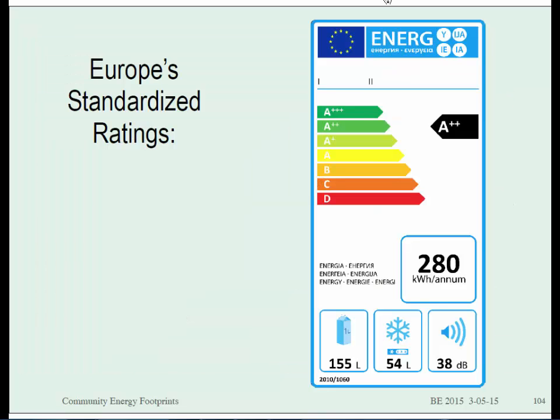As HERS ratings are not particularly informative for most renters or buyers, as Keith points out, a final layer of processing gives deeper meaning. Is anyone familiar with the European standard? So this has actually been codified and is now in use across the EU, and it's actually required. So EU standards now require all homes advertised for sale or lease to disclose their energy rating. The rating is also an asset rating, though it has a projected kilowatt hours per annum based on typical occupancy. So again, they are putting this back into easily digestible terms, showing you where this house stands, but also putting it into energy terms so that you can translate this to cost.